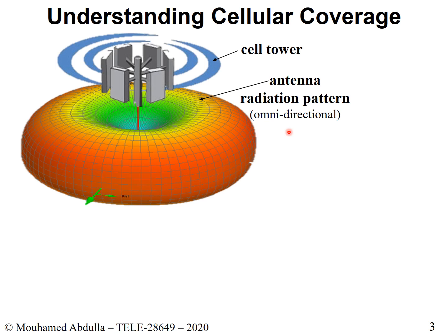Perhaps you recall when we did the gain of an antenna, we saw that we refer to the gain of an antenna as dBi. You have the subscript next to the dB with an i, and it means that we measure the gain with reference to the isotropic antenna. That's why we use dBi. In this case, we're not looking at an isotropic antenna. We're looking at a real-life antenna, an omnidirectional antenna, an antenna that radiates in all directions.